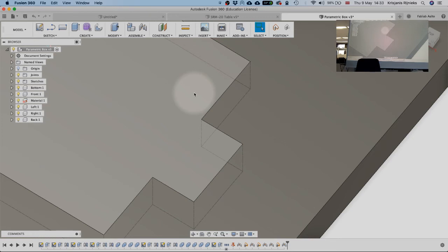So you see, it's approximately 4. Now it's actually exactly 4. It's just that my caliper skills are not the best, and you measure the diameter, so you always need to know the diameter of the tool. This one also has 2 flutes, meaning that it has 2 cutters. So that is also one important property to know. The other ones are how high the part is that is able to be cut, and the overall size, but we're going to get to that. So now, let's use this 4mm tool.